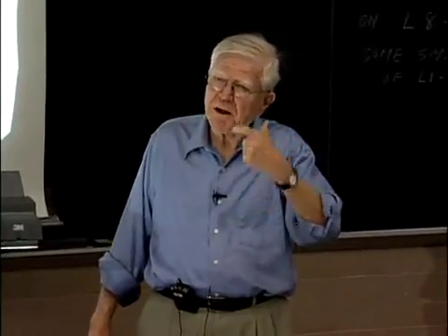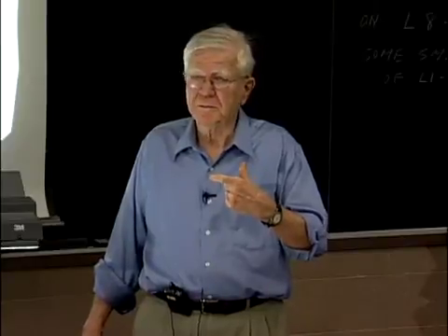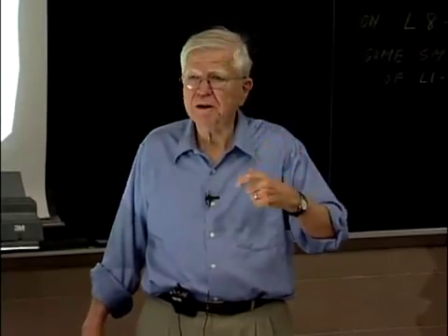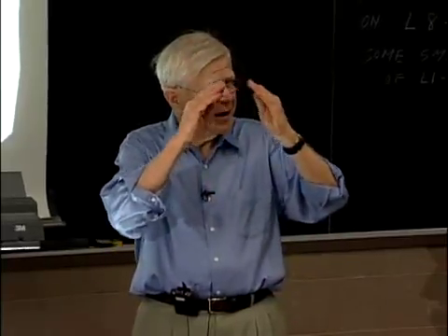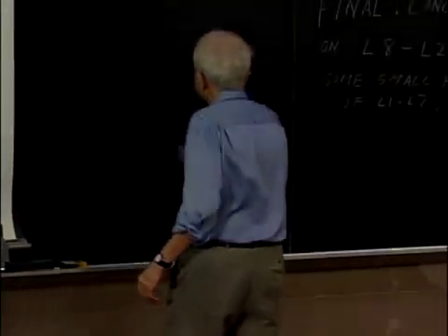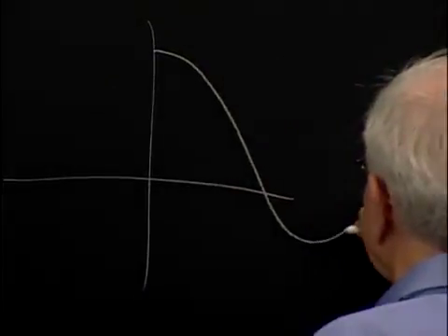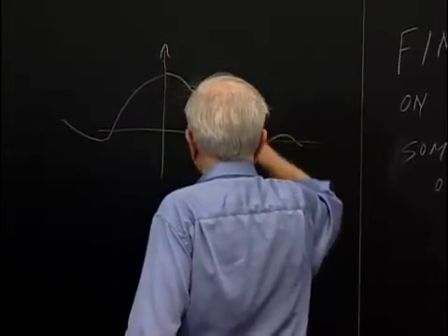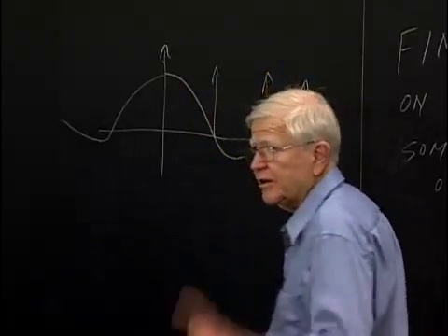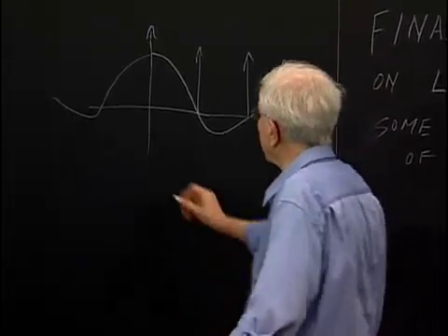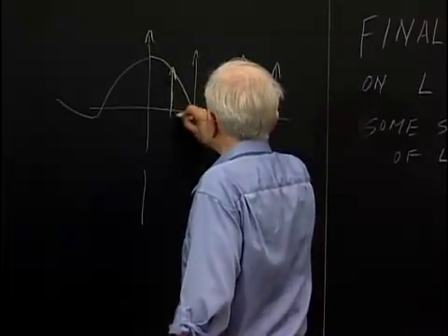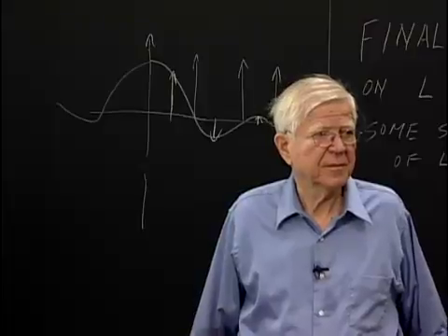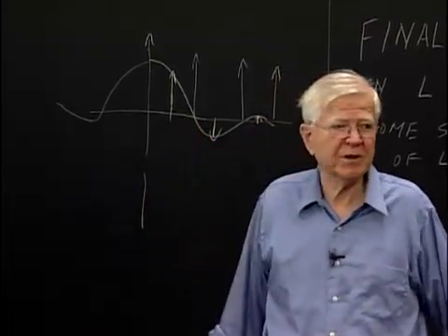If you now say that the impulse response of the channel is about 1 tap long, and then you say, how many taps do I need to represent it? It's an interesting question, because if the impulse response is 1 tap long, and you filtered it to look like a sine x over x, the impulse response can look like this. So you have 1 tap here, 1 tap here, which is 0, 1 tap here, 1 tap here, which is 0. But if you've gotten your spacing off by half a cycle, what do you have then? You have a tap here, you have a tap here, you have a tap here, and you have these taps which are going down as 1 over time. So in fact, modeling this kind of thing with 1 tap would be terrible.